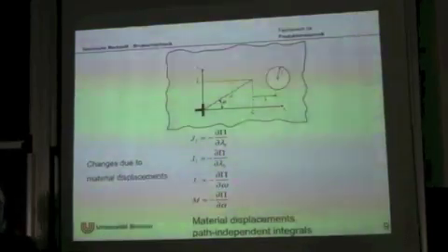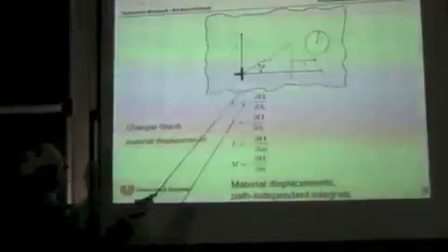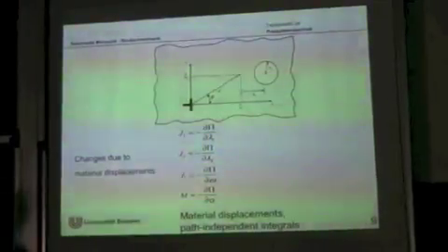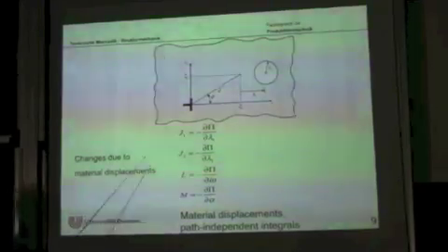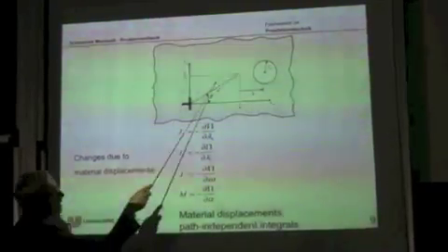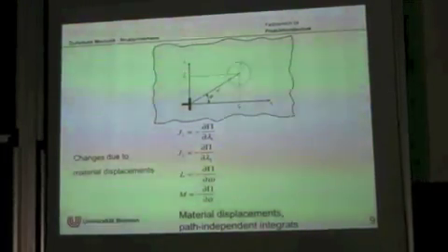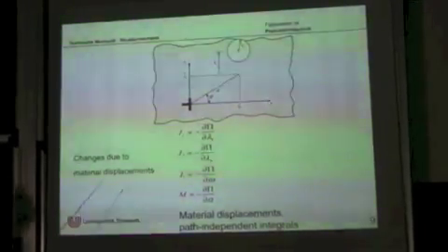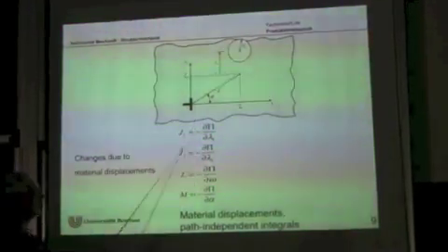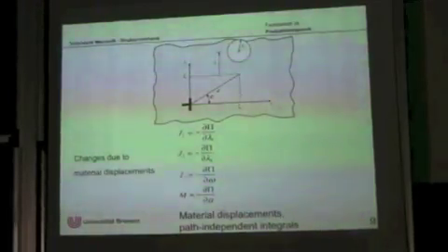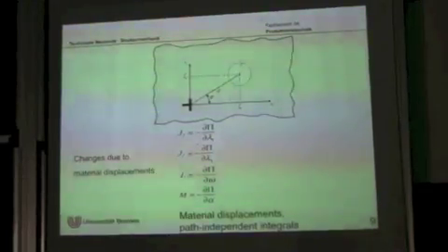If you consider the change of the energy, you have two configurations. One is the hole at position x1, and then it's shifted. That's a different configuration with a different energy, and if you subtract both energies and divide by lambda 1, you have just the J integral. You can calculate the force on this defect by a path-independent integral including this defect, and you can find immediately the force on the defect with the hole in this direction, what drives the hole in this direction. Going back to the initial configuration and applying a translation in x2 direction by lambda 2, you have the integral J2, because J is a vector-valued energy release rate depending on the direction.